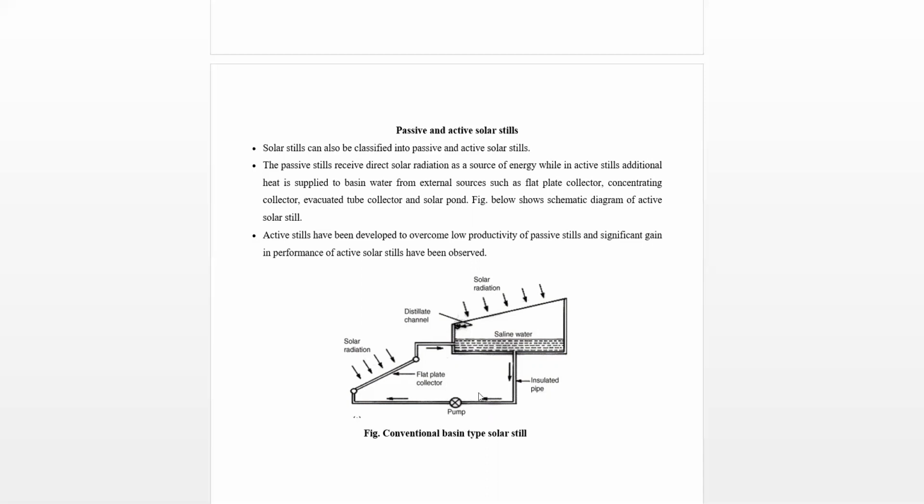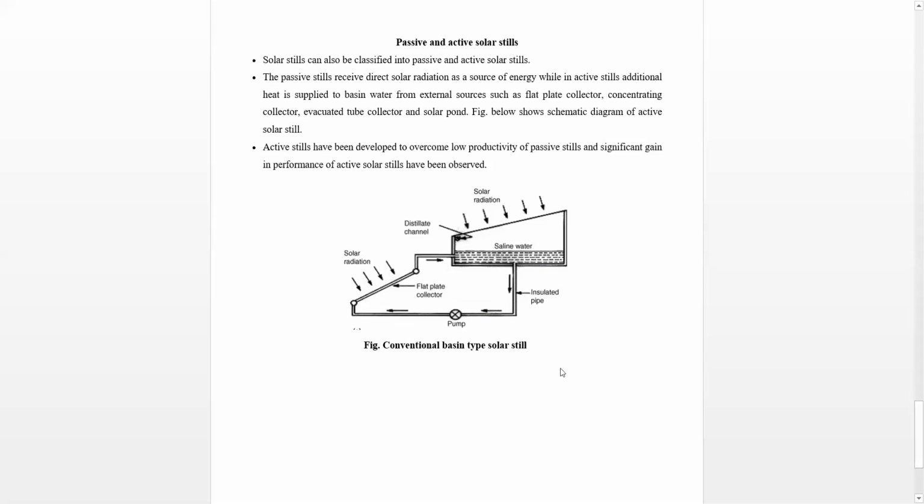And the energy for this pump can also come from the solar panels. Like a 60-watt, 12 volt and 5 ampere direct current DC pump can be used, and the power to run this pump can come from the solar panels through the photovoltaic process. So not the conventional energy is used; the energy used to run this pump also comes from the sun, right? So this concludes this topic.